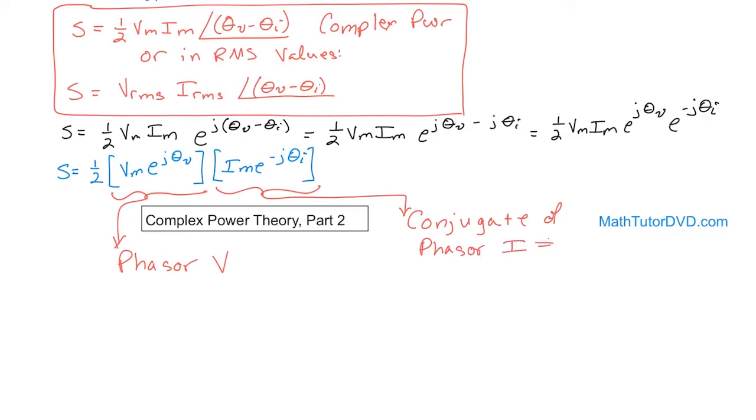And we call that the conjugate in terms of complex numbers, I with an asterisk, right? So let me finish the punchline here, and then you'll see how I'll review it all, and you'll see why it's useful. This is 1/2 times the voltage phasor going through whatever circuit component you have, times the conjugate of the current phasor going through whatever circuit component you have.